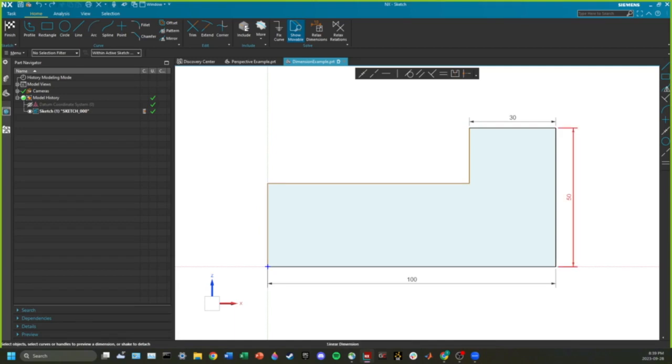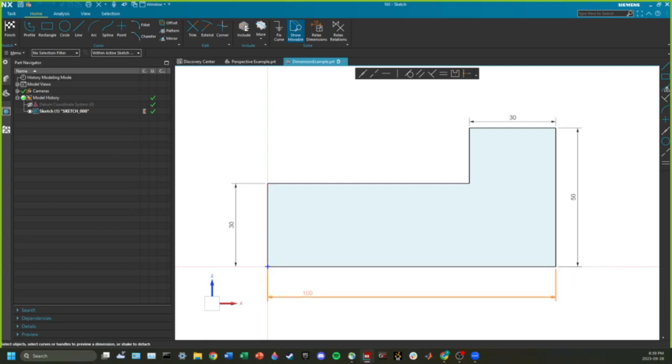As a rule of thumb, which I like to do a lot when I'm modeling stuff, instead of dimensioning the line itself as whatever it is, I'll dimension it from an axis. It's just more absolute this way, making it from the origin coming up. You can make it so that an individual line is referenced to itself, basically, but if you have something really complex, it might get difficult. You might want to go to something like this, where everything is based off of a single point.